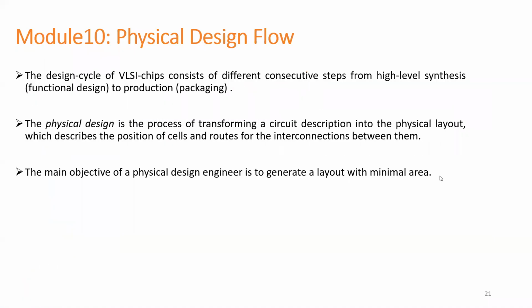So physical design is the process of transforming a circuit description into a physical layout. So the logic schematic will be converted to physical layout with three targets: power, performance and area. All these targets should be within limits. So the objective of the physical design engineer is to meet these targets. Using the automated tools, the physical design engineer will convert the gate level netlist to physical layout.